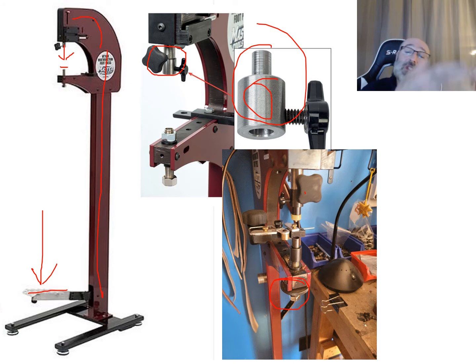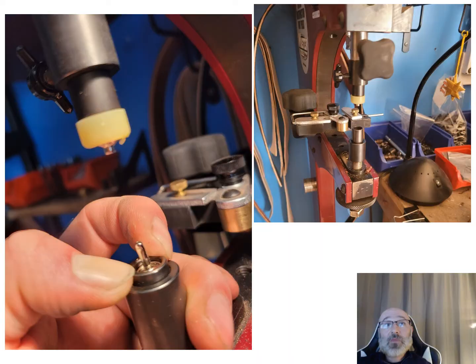And we can even take it one step further, 2 or 3 steps further actually, when we're talking about riveting things and automating it and making it a little bit easier to save us some time. So with that, you can take a look here. Here is my double rivet. You can see I have this top piece. It's a pretty simple design up top here. Not all of these are going to be a ferrous material, so I can't necessarily use a magnet. What this is, is a little piece of rubber up here that just folds over the top head of that rivet right there, holds that in spot, and on the bottom, this is spring-loaded right here, so it makes it blind. You can see when it's all the way up, you can't even see the stem part of that bottom rivet right there. Holds that in spot.